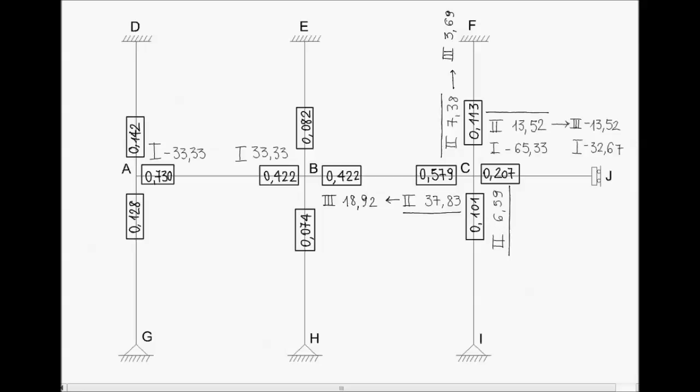We will obtain these second bending moments. Then, considering the carryover factors, we will obtain these third bending moments. They have the same sign of the second bending moments.